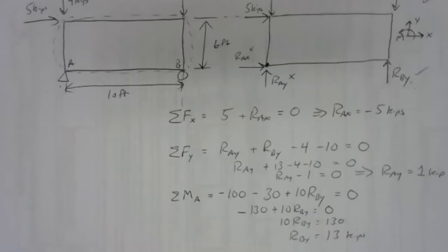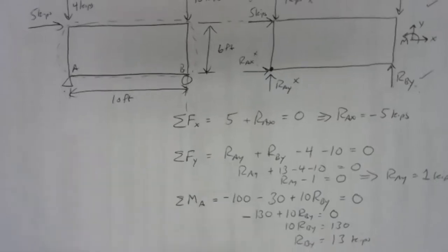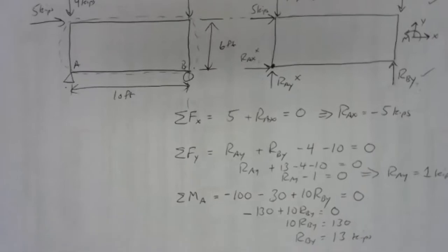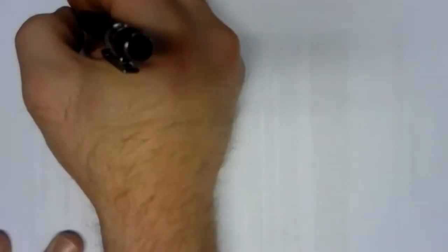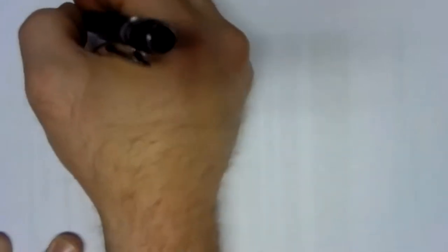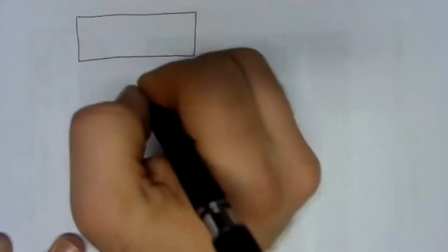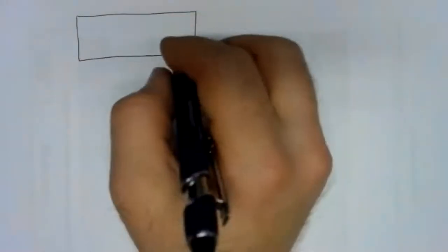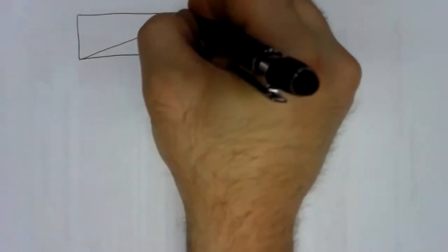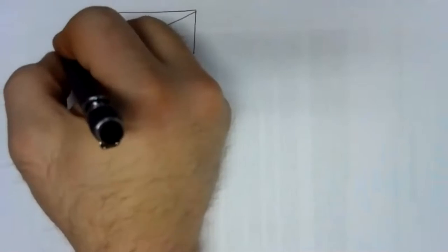All right, so let's take it a step further here. To go further, we now have to go into the internal problem. The first step in working with the internal problem is to redraw your truss with the support forces in. So I'm going to redraw this so I have a nice clear picture to look at. And I'm going to draw the internal structure too. And let's see, yep, that went up and to the right here. So we have A, B, C, and D.